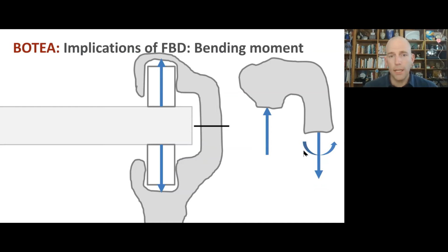And we'll need a moment at that cut surface, and that's through the interactions between this portion of the component and this portion of the component down here. So really, this moment and this force are going to represent a pressure distribution. We have more tension on this side and either some compression on this side or just less tension on the outside edge of that element.